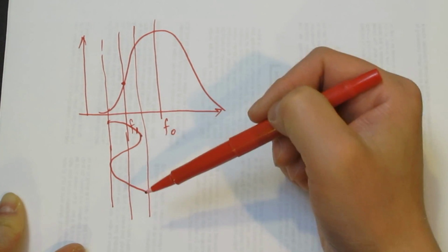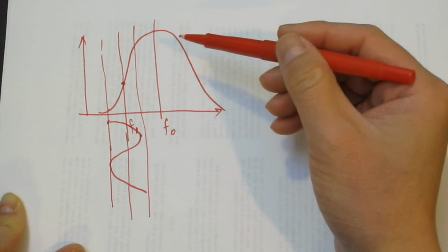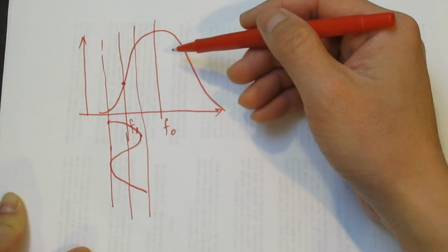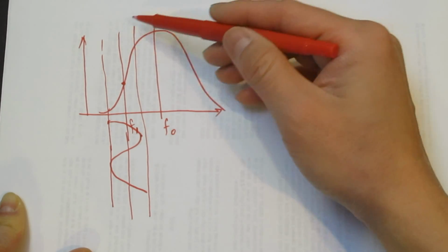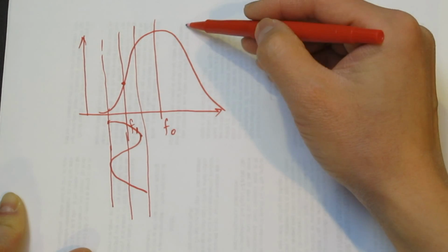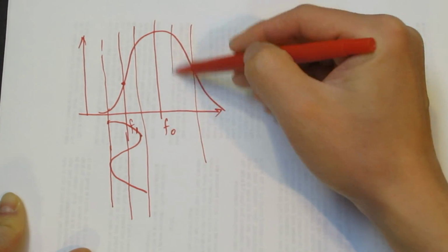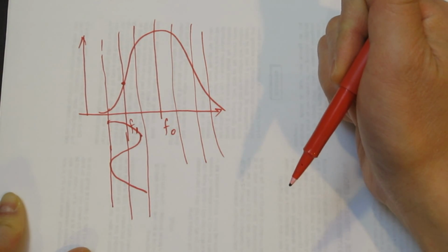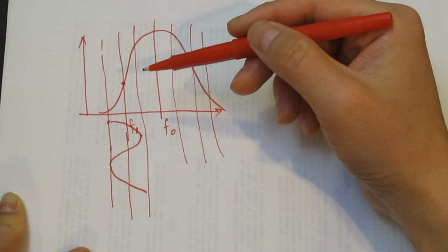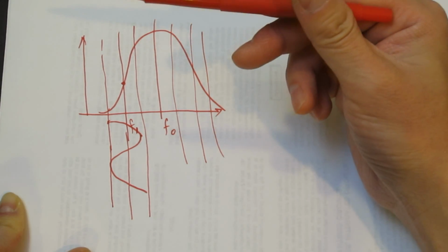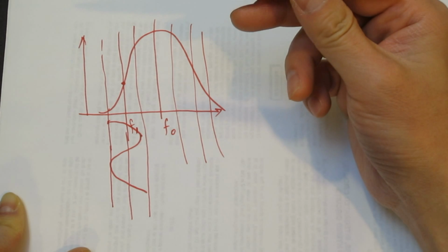the FM signal. And as you notice, because the filter is essentially symmetrical, we can detect the FM signal using either the upper band here, for example, or the lower band. So this is how we're going to be demodulating the FM signal. Later on, I will show an example of that.